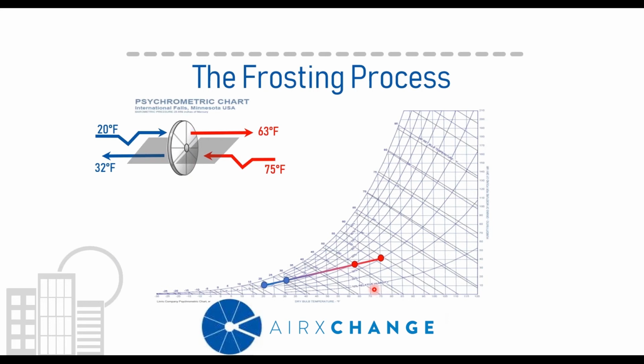Energy recovery is fairly unique in this regard because as the exhaust air gets cooled, it's also dried, which means the leaving air naturally wants to move away from the saturation curve. It's because of this unique process which really minimizes the risk for frost. So keep that in mind. The thing to take away from the slide is that in order for water vapor to condense, this process line has to come in contact or close to contact with that saturation curve.